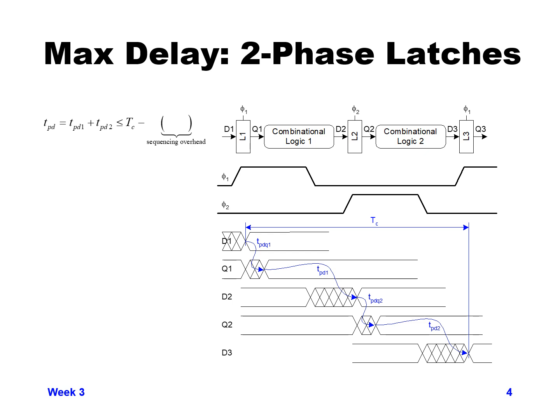We want to make sure that we usually try to make it so that the data gets to the latch around the time that the latch is opening, so we can use the full amount of logic. It's not sitting there waiting for the latch to open, and we don't want to go too far into the latch time being open or we start running into additional problems. So we'll look at that right now.